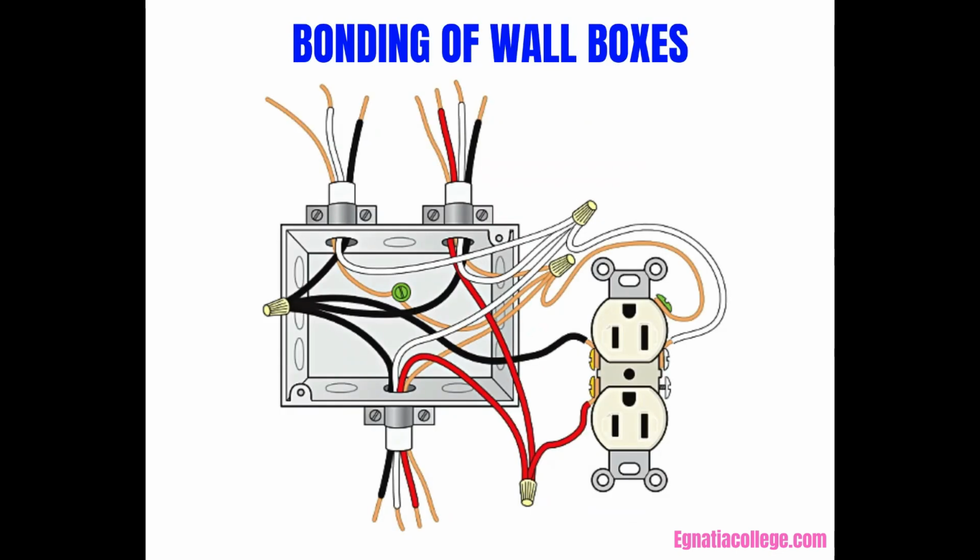The specifications for the residence state that all metal boxes are to be bonded. The bare conductor included in non-metallic sheathed cables, NMSC, or armored cable, BX, is connected to the bonding screw in the box. And, for receptacles, carries on from the connection in the box to the bonding screw on the receptacle. This conductor is used only to bond the metal box. This bare grounding conductor must not be used as a current-carrying conductor, since severe shocks can result.